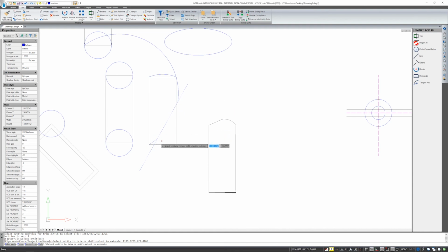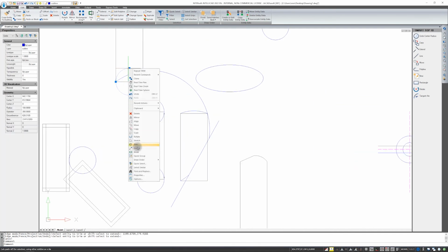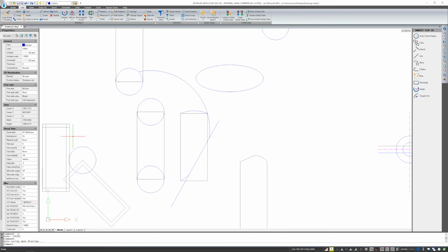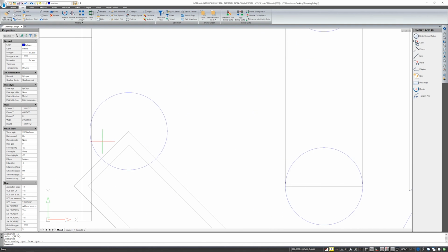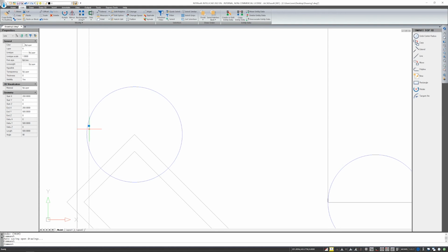If I still want to get rid of the two pieces that are now marked, I just have to remove them. And in a similar way, I can remove these two lines from the second circle, from here. And now also remember that when you're selecting the circle and what should be cut, indicate it, click at the end with the right mouse button, or Enter, and exit the option. When it comes to cutting in this area, it is quite important what you choose to cut out. Please pay attention. If I want to cut this piece of the circle, I mark this line because it will cut this circle. I confirm it with Enter and show that it is not there.